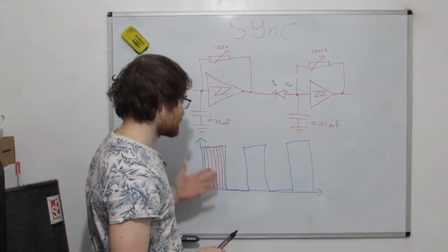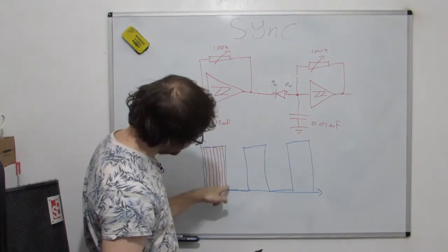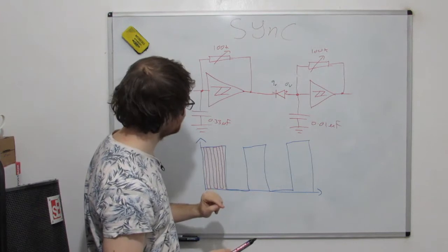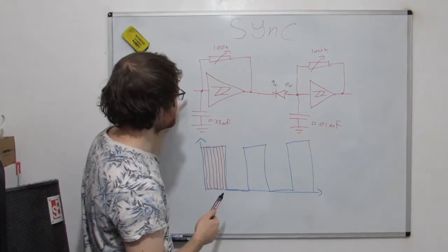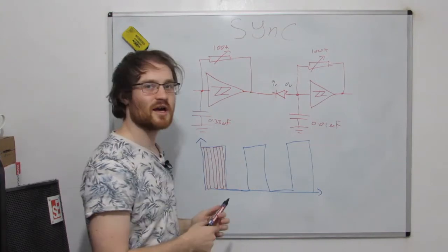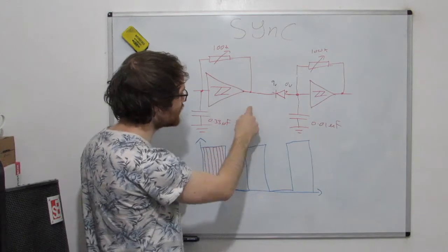Okay, nice. So does that go on forever? No, it doesn't, because there comes a point where this output goes low. This is charged up to the point where it registers at the input of here as logic high, and so this inverts and flips the output low.